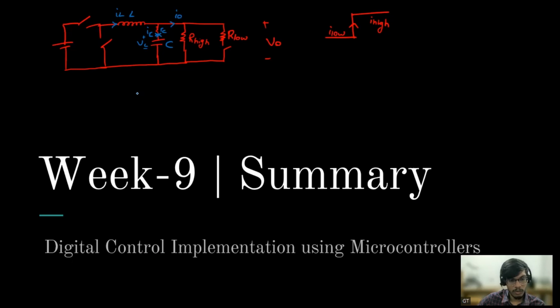If you see the voltage profile, I'm considering very little ripple. At this instant, there will be a step down because of this RC, because this load current step is being provided by the capacitor. Instantaneously this capacitor is providing the current, and there will be a drop across this RC, which will be reflected in this V naught curve.